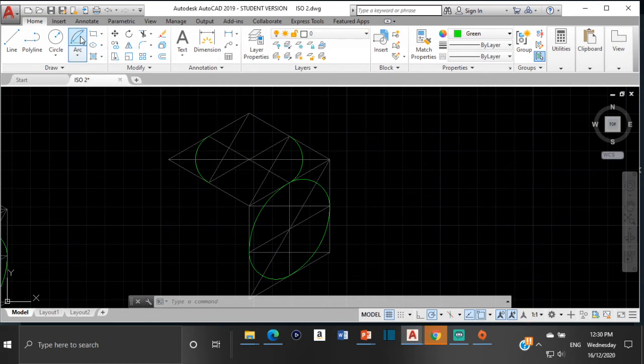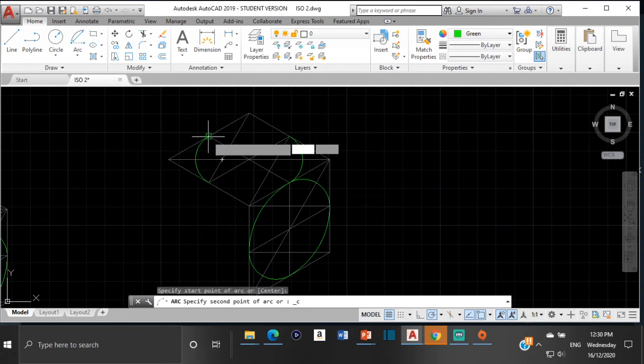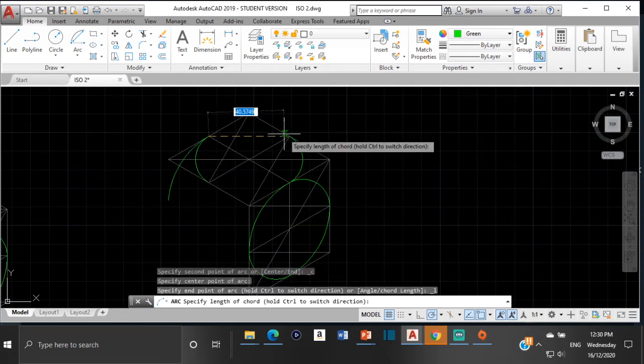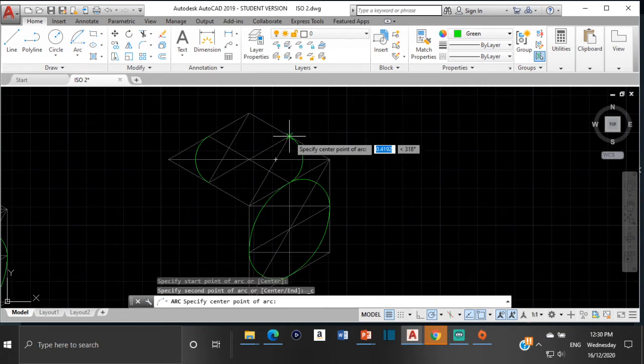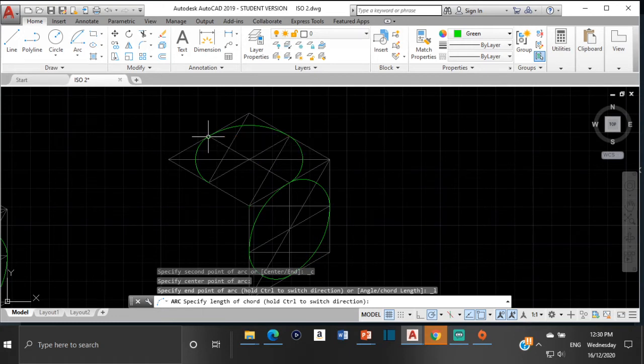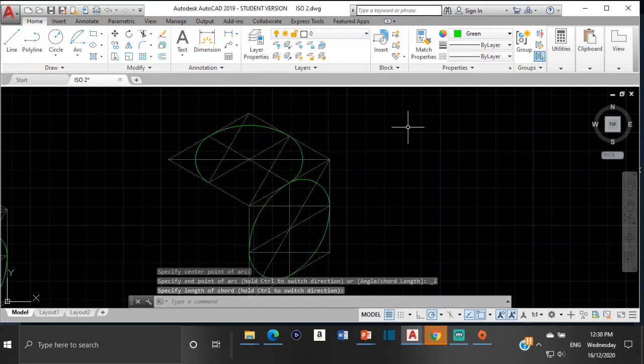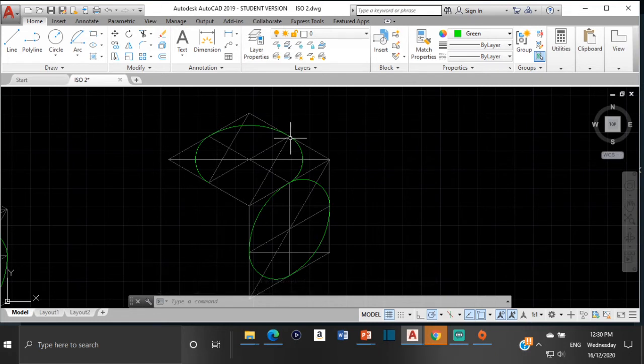So we want to get this cut over here. So start center length again. Let's start here. Use this as the center, and end right there. Okay, what we just did was select start center end. We start here, use this as the center, and end right here. If you're doing it manually, compass point here, open the compass to this point, and scribe your arc.